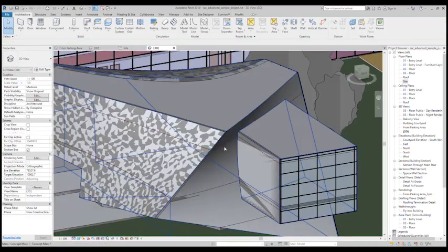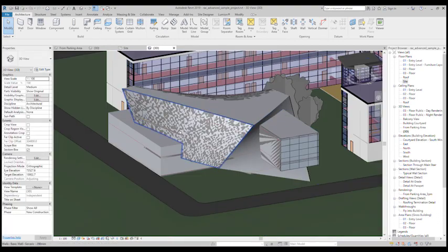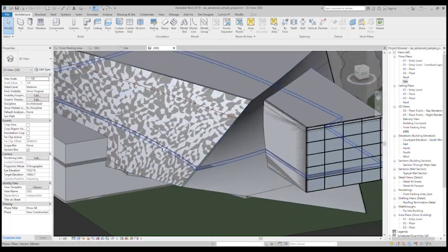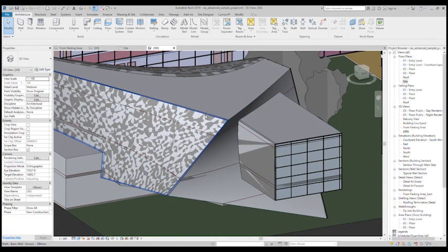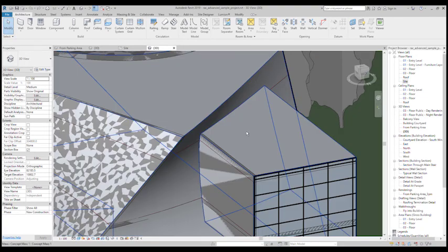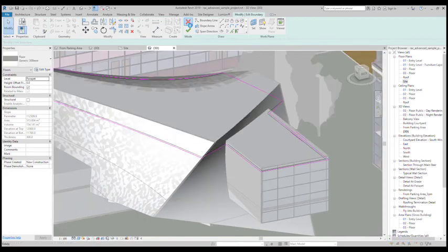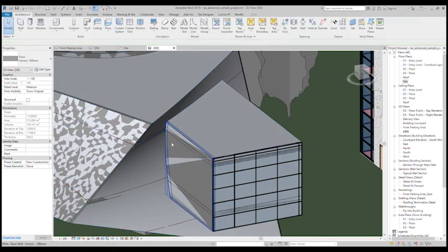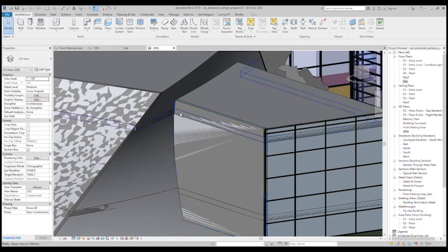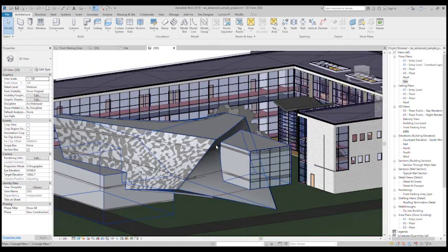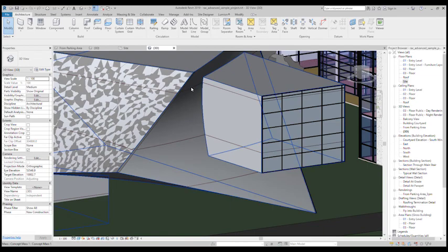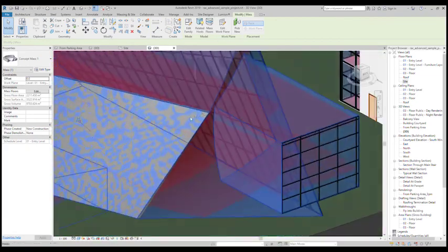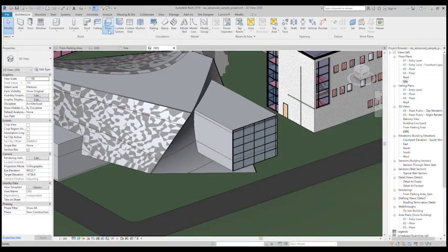But this is sometimes a little bit laborious to do, because now if you've got a 20-story building, you have to go and edit the profile of 20 floors. There's a way of doing it quicker from the beginning. I'm just going to undo everything. Cancel that, edit, cancel. Sorry, to go back a little bit, before we place the floors. So here's the mass floors. So now I'm going to redo the floor by face,